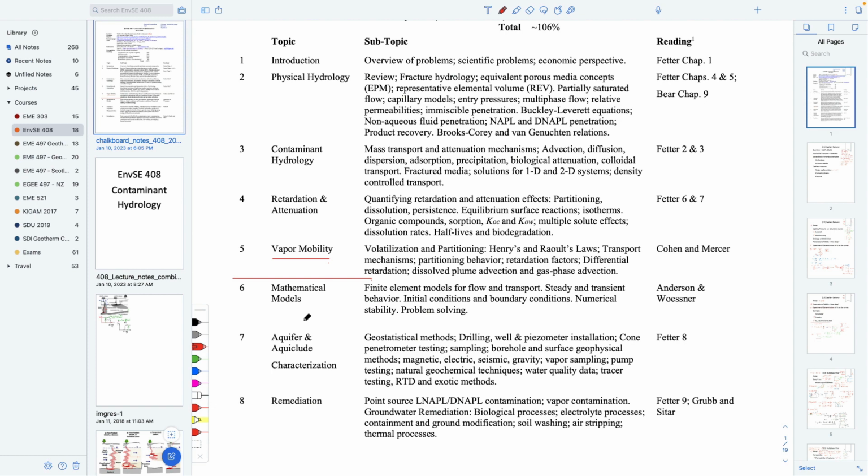We'll talk about how you go about getting that information to be able to put it in the nice, neat little assignments that we've had, where we've always assumed that we know the stratigraphy, we know the concentration distribution, and we know what the properties are of the subsurface. And so the method to do that is to drill some holes, to do some sampling, to put in some instruments like piezometers, and perhaps to use pump testing and aquifer testing.